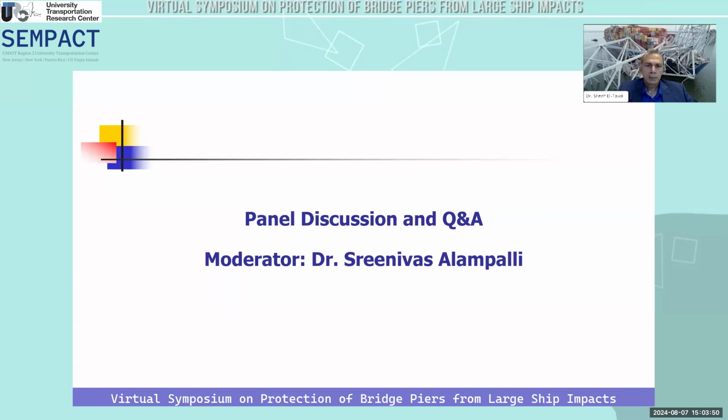Yeah, in my experience, the cost of a longer span is less than the cost of a shorter span with expensive pier protection systems around it, such as dolphins and islands. A longer span is almost always a less expensive overall alternative. Based on your experience, can you give me a threshold where it becomes more cost beneficial to have a longer span?